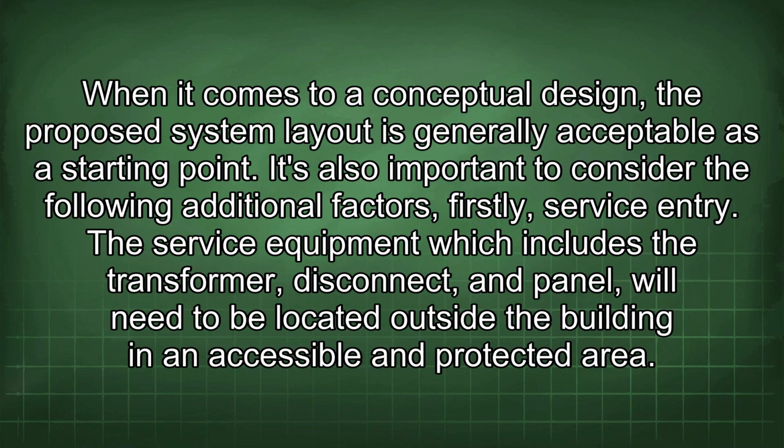When it comes to a conceptual design, the proposed system layout is generally acceptable as a starting point. It's also important to consider the following additional factors. Firstly, service entry. The service equipment, which includes the transformer, disconnect, and panel, will need to be located outside the building in an accessible and protected area.